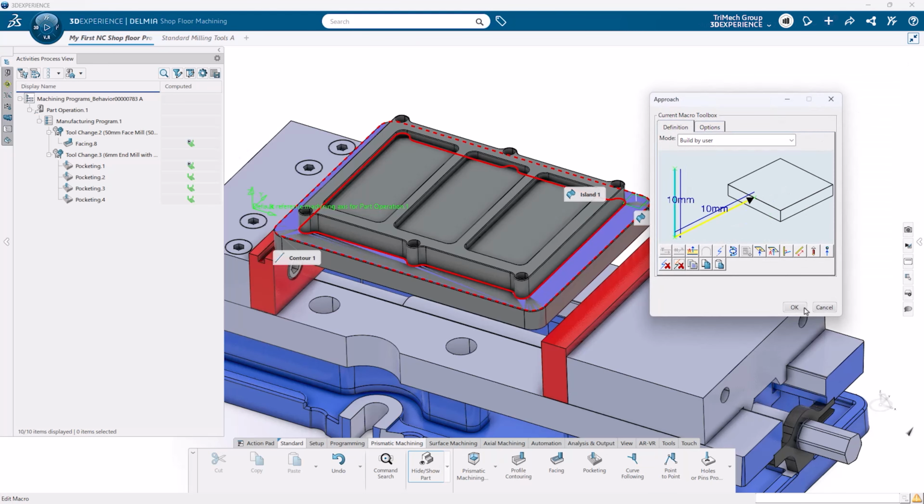This red mark indicates our retract is causing some issues. We are also receiving a message indicating that there are faults with our toolpath, and there are some dog ears of missed material at the corners. So let's exit the simulation and review our operation.